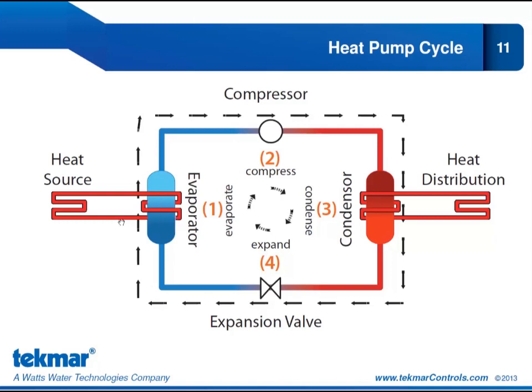At the evaporator, the heat is transferred to the refrigerant inside, which boils to become a low temperature vapor. The vapor is then compressed, which reduces its volume and increases its temperature. So now I have a hot vapor, which passes to my condenser.